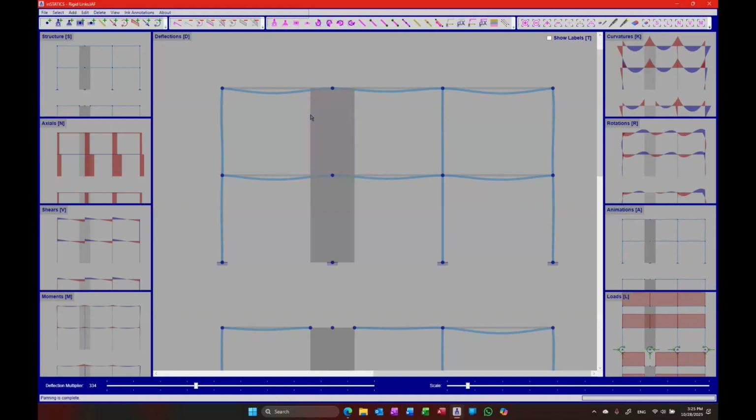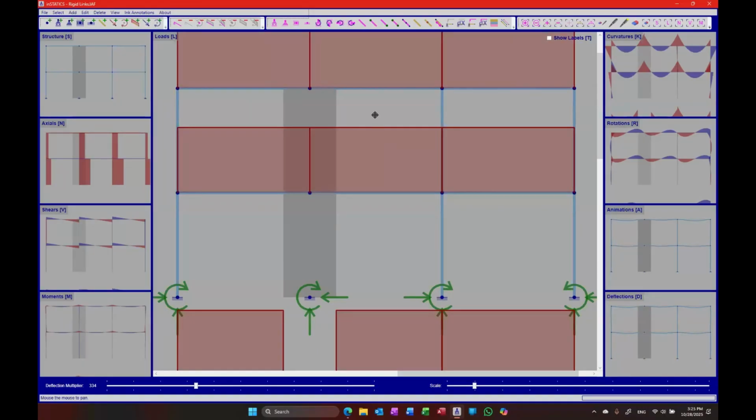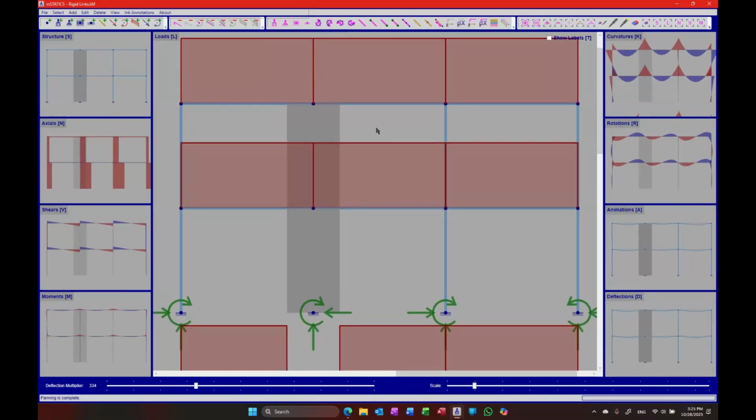Look at this. This is clearly a uniformly loaded structure. One thing that you will immediately notice is the uniform load goes all the way to the center of this shear wall. But in a real world application, obviously, we don't have people, let's say if this is live load, right? We don't have people walking into the shear wall. So this is overestimating how much load we're going to be putting on the structure, right?